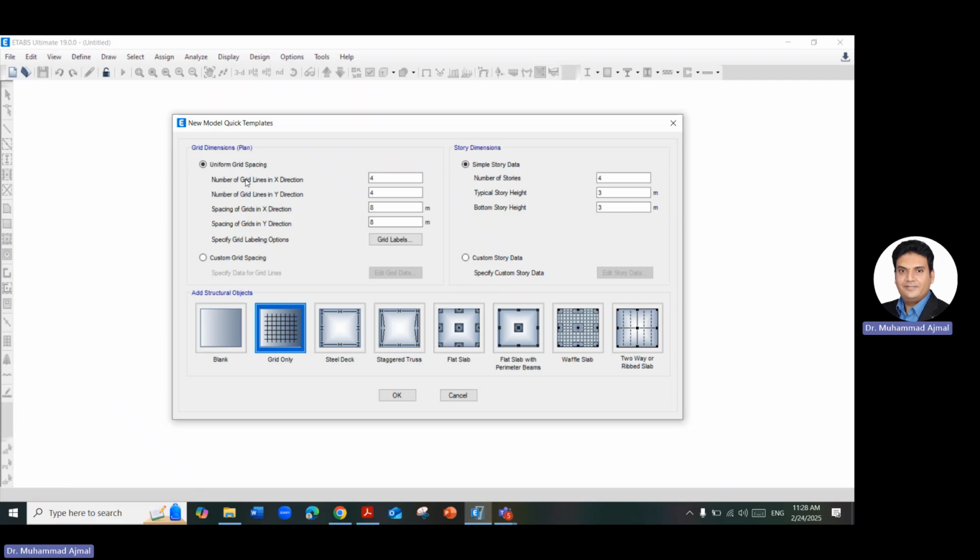When you are modeling in 2D, you should model your two-dimensional system in the XZ axis. Okay. And consider the other axis as your third dimension. Now, if I model this beam in the XZ direction, I will be considering up as Z and this as X.